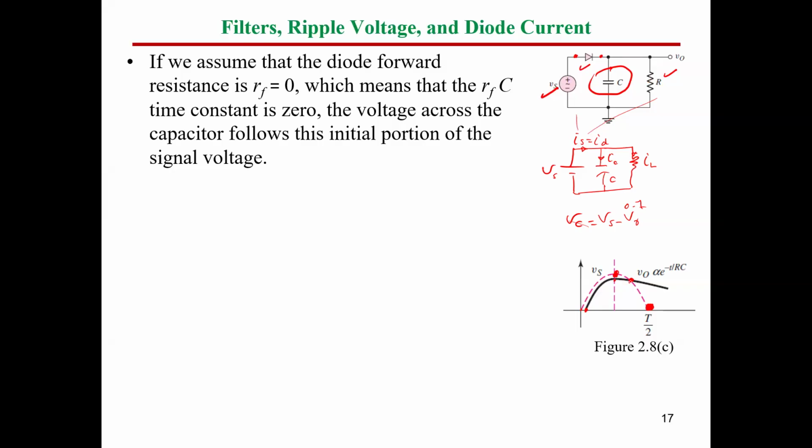At this point, guys, as you can see, the capacitor volt equals the supply volt, or even the capacitor volt is less than the supply volt by the magnitude of V gamma. This means the volt here is equal, which will try to force this diode to be turned off.